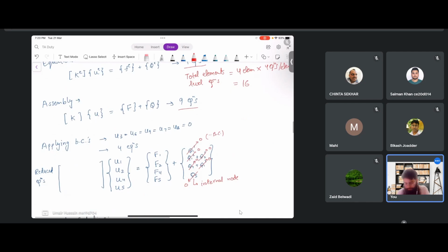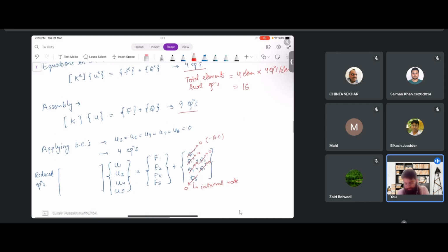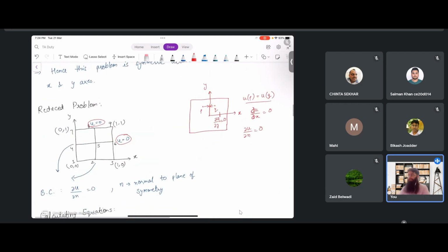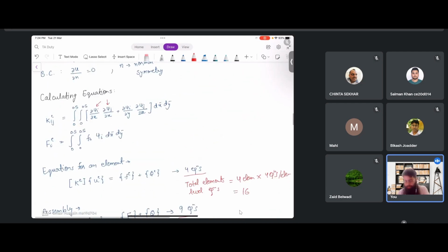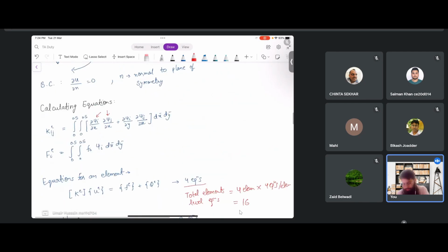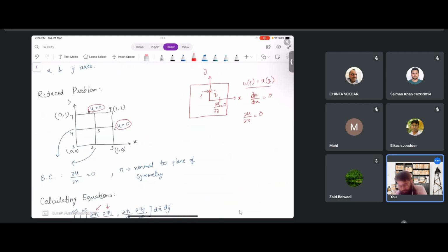All right. And since we have been given a boundary condition also, we might have discussed this in 1D FEM, how to apply boundary conditions and get the condensed matrix and vector. So after application of boundary conditions, out of these nine nodes, we know the values of these one, two, three, four, five nodes.